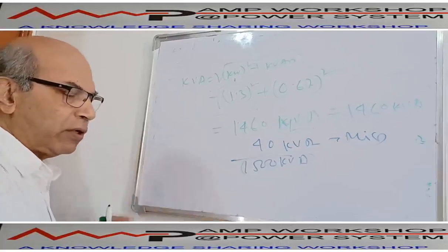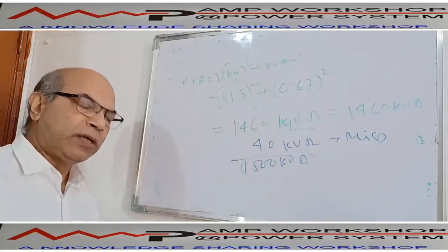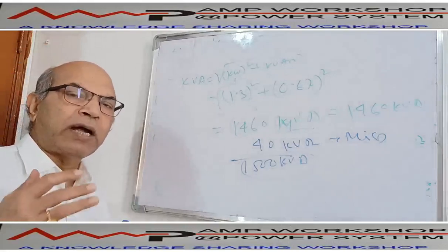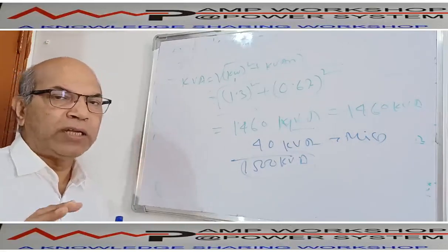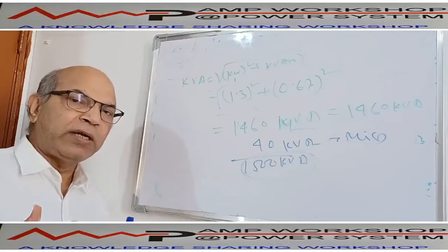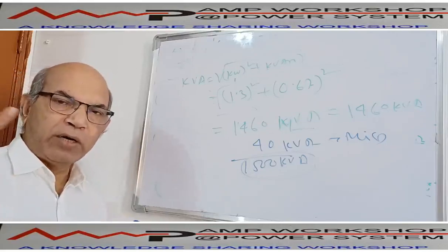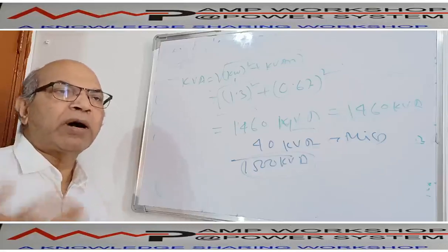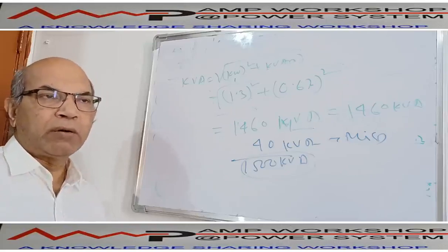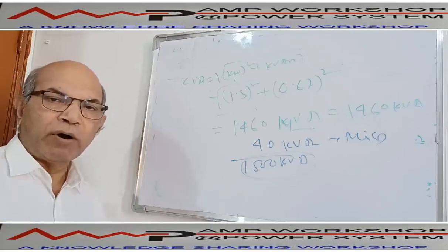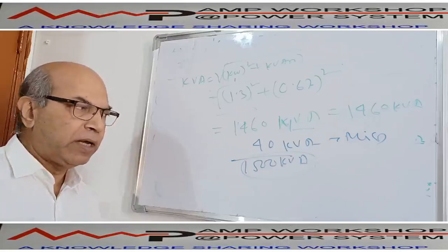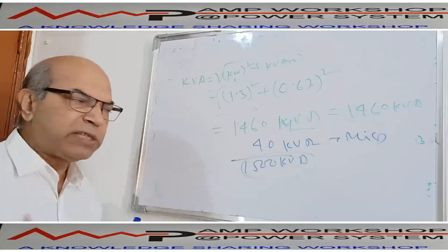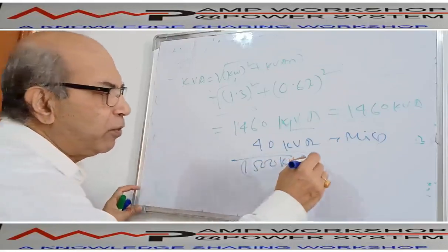Now normally we do not consider the apartment size exactly. We put some margin because today you are putting this transformer, and a transformer we never allow to run on the same full rating. Generally we allow 80 to 90% rating, and we keep some option if other loads come in future. Maybe some other contractor will be coming to work over there, they need some power, some welding work, some breaking work, all this requires power supply. So generally we consider the transformer running at not more than 80%, with some spare capacity for other purposes, we generally put 20% margin.